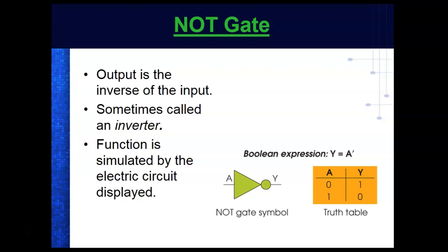So if I was to come up here and put some control device like a push button, and I'm going to come over here and use a relay, and I'm just going to call it R. And then I'm going to come down here and put a light right here. When the button is not pressed, I want the light to be on. When I press it, I want it to go off. What type of contact would I put right here? So that's a NOT. A single, normally closed contact.